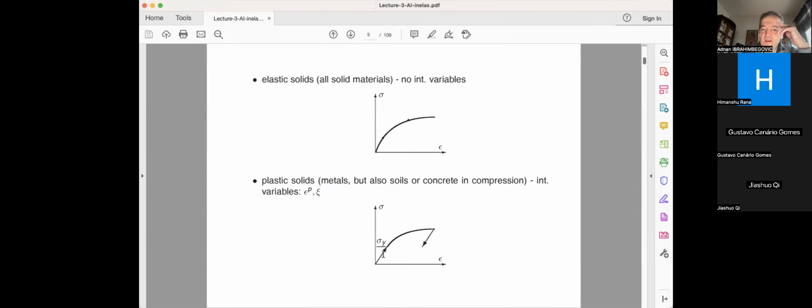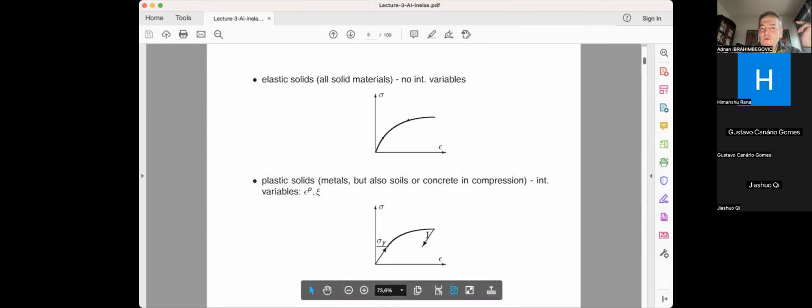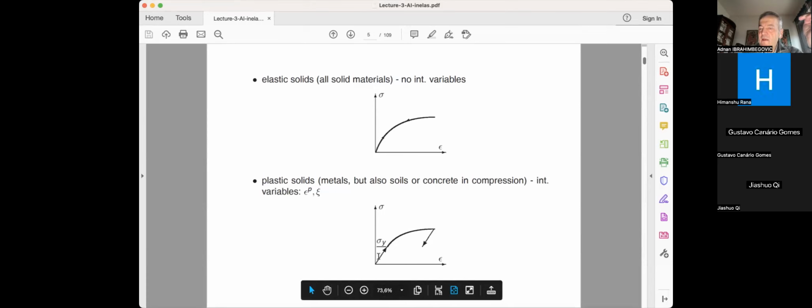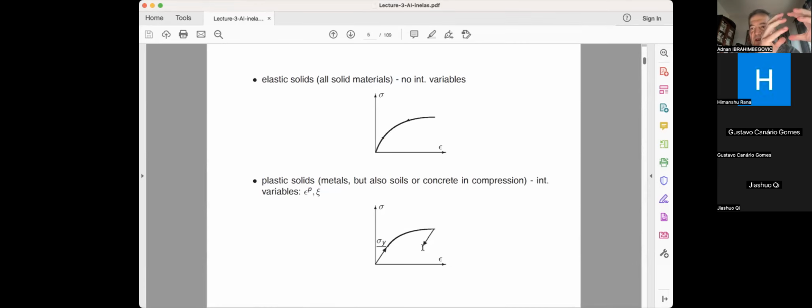If you know, then you do identification and so on and so forth. So you push this to the maximum level of the loading where you want to go with the test, and then you start unloading. Now, contrary to elasticity, where you follow the same path when unloading and go down to 0 stress and 0 strain, here you start unloading in a way which is exactly the same as elastic. Namely, what happens, I mean, one interpretation of these phenomena is that basically first you introduce elastic deformation, and then you introduce the plastic deformation.